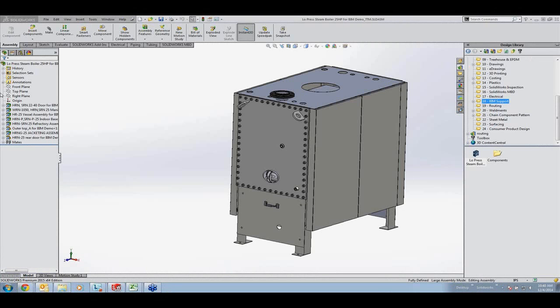All right. Something else that's supported by weldments is gussets. In the past, you wouldn't be able to make a gusset between two components that have a space in between them. But now that little space, that gap there, it is not a problem. Go ahead and create my fillet, or my length for my width. And once again, I'm going to pin this so I can reuse it. There's a gusset with a gap.